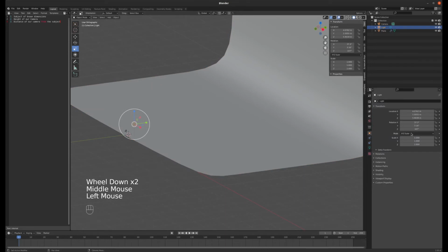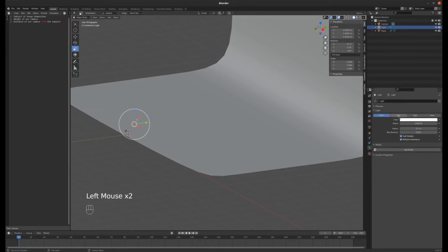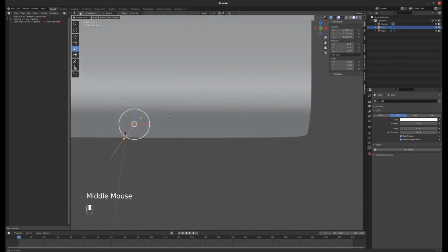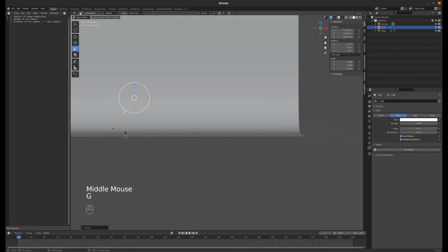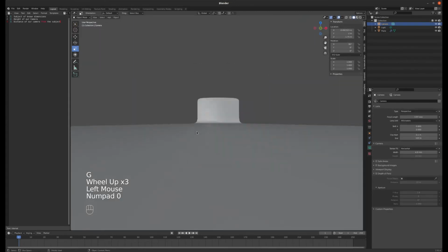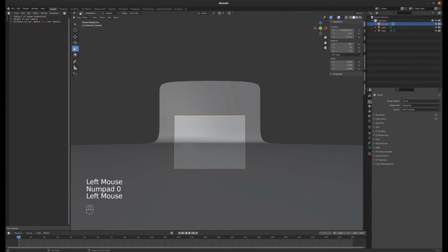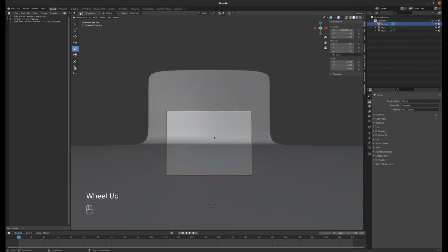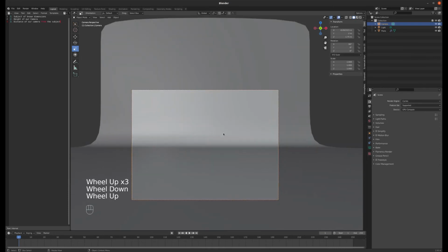All right, I'm going to change my light into a sun instead of a spot lamp, because a sun's position doesn't matter, and it has no falloff, no decay. We'll have to turn the strength way down so that we don't blow everything out, but basically that's going to help me in illuminating this background. So let's look through this. I'm going to repeat, as always, I'm in the Cycles renderer because it's going to deal with shadows and light in a more accurate way.